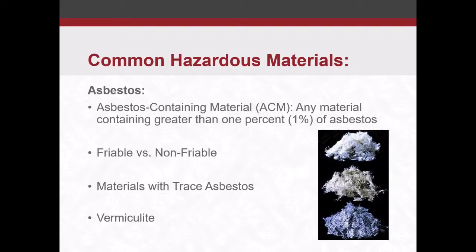All right, so taking a little step back, as we're headed in the direction of doing an abatement design, what materials are we concerned with? Very commonly, just because of heavy regulations, there's set protocol and procedures, and they've been established for a while. First up, there's the asbestos. So asbestos containing material, we're looking at any material that contains greater than 1% of asbestos.